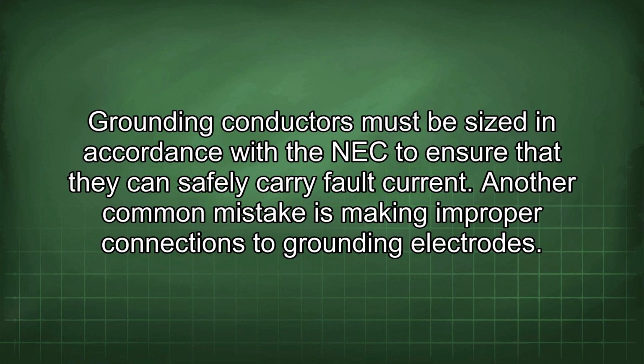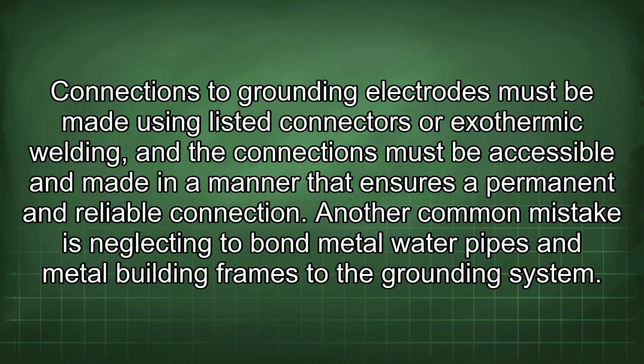Another common mistake is making improper connections to grounding electrodes. Connections to grounding electrodes must be made using listed connectors or exothermic welding, and the connections must be accessible and made in a manner that ensures a permanent and reliable connection.